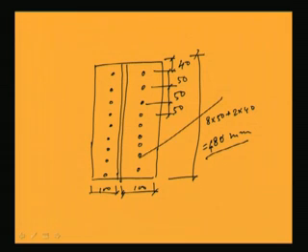These are 20 diameter PDS, power driven shop rivets, and this is hot. That means initial tension is considered, and this is the 100 mm width, because ISA 100 by 100 by 10 has been considered. So in this way the design can be made.